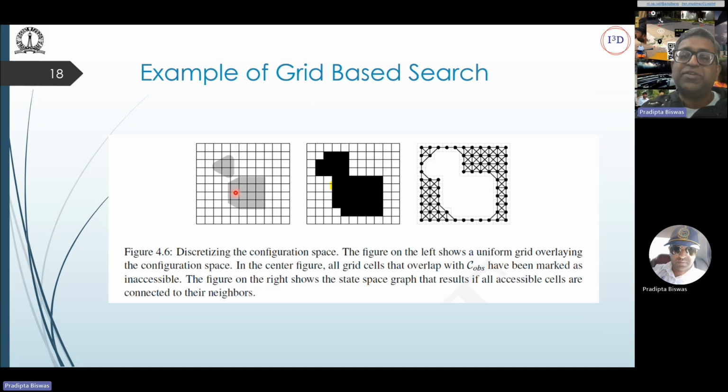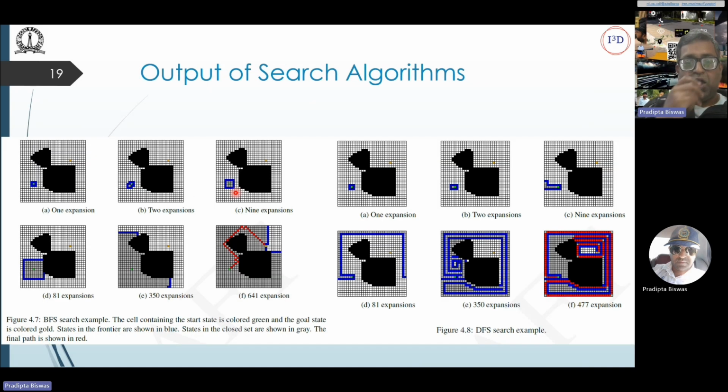So if I keep on reducing the grid size, the algorithm will take too much time or will not run. So how can I know the best size of cells, so that I can still make a motion path through the gap between the two obstacles? In this particular size, we cannot do that.